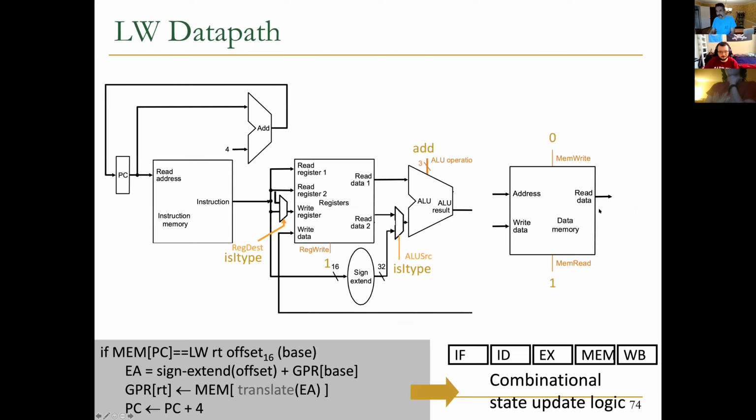You see now a new element that you definitely need to add in this microarchitecture, which is data memory. And somehow you need to wire things in order to implement either load word or store word. For load word, you need to locate the right memory address and load the content of it back to the register file, to the right register. For store word, you need to again find the right address and write to the memory the content that you get out of this ALU, right?